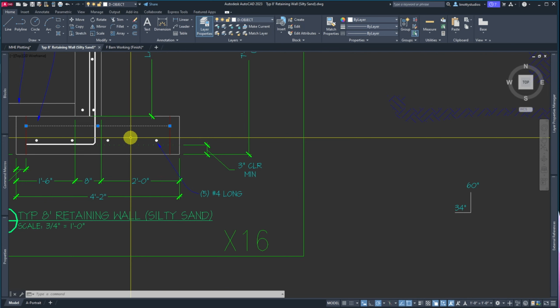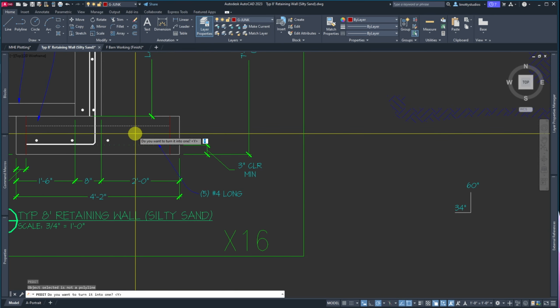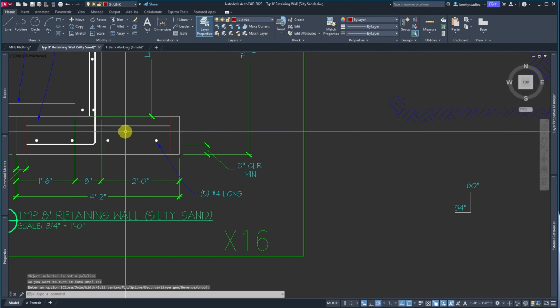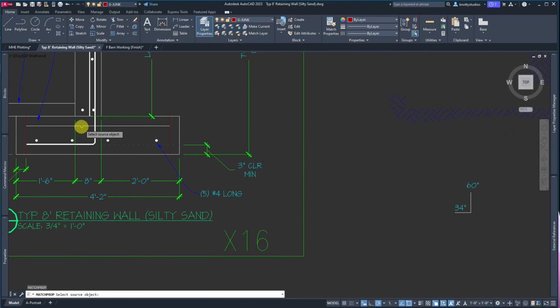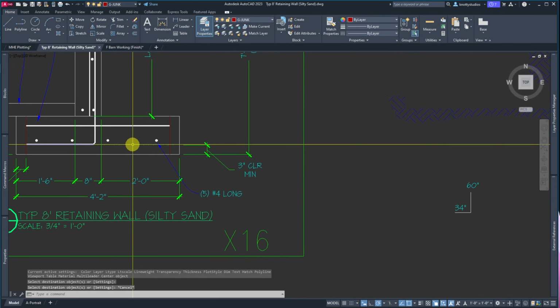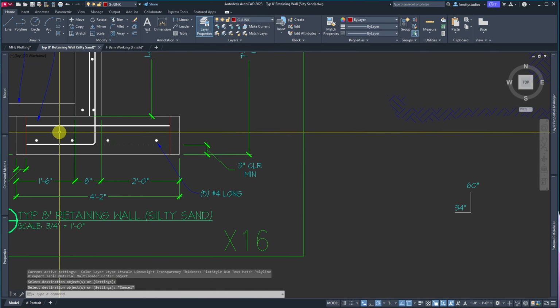So I'm going to go PE. Oh, that's right, E, P, enter. Do I want to turn it into one? I've already got it chosen, so I'm going to hit yes. And then just hit enter again. You could, if you knew it, change the width. And I do know it because I'm doing a bunch of these, but I'm not going to use it because you don't know it. So MA, pick this one, and it's the same. Now you have that bar set.